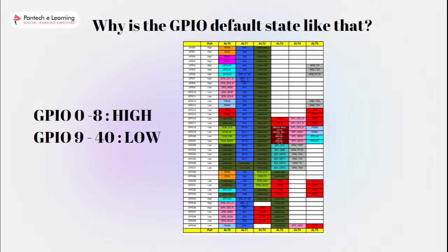Now what is the value of this pull up and pull down resistor? Unfortunately, it is not possible to know exactly, because the actual Raspberry Pi hardware is not open source. Most of the software is, but not the hardware. So there is no way to know directly from the Raspberry Pi Foundation. However, with some tests published by users on the internet, we can approximate that this internal resistance is about 50k ohm.